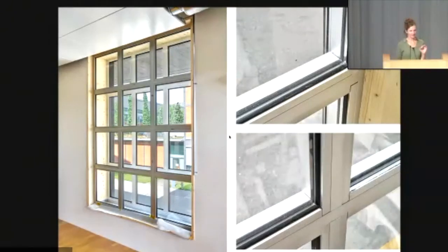So this is, in my eyes, a huge potential that we haven't even tapped into. What we did here is that we took these existing double pane windows that are thrown out of every building because they're not good enough anymore, they let out too much energy and so on. So these windows we just took and added a third pane. This is not untypical; in historic construction, this is done sometimes. You have an existing double pane, you add a third pane, a new spacer and new gas. And so we put that back in. So this is one upgrade we tested.